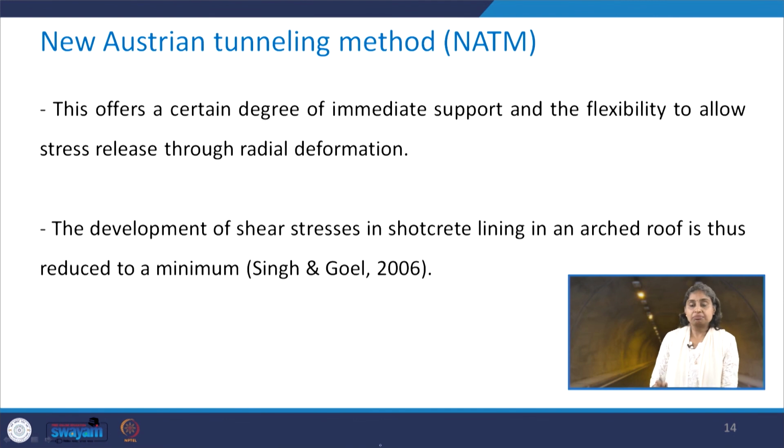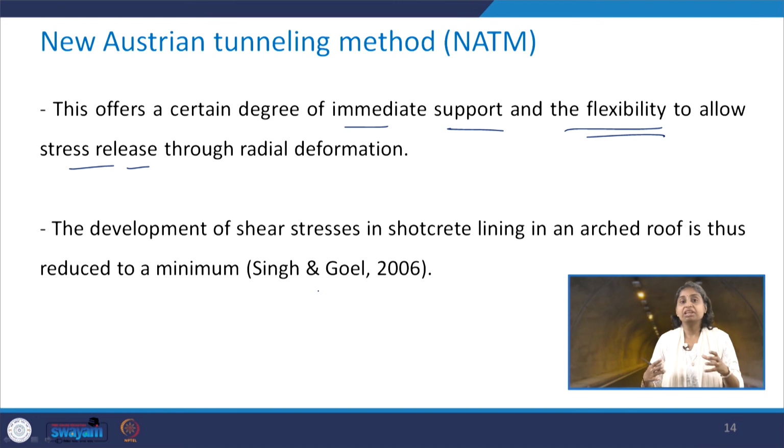Now, this kind of support system offers a certain degree of immediate support and also the flexibility, so that the stress release can be allowed through the radial deformation. See, excavation is made. If you do not allow any radial deformation to take place, a lot of stresses are going to be restored. What will happen if you allow the radial deformation to take place? As the deformation takes place, the stress release is going to occur.